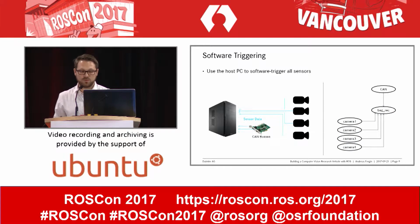The normal solution is setting up sensors at defined cycle rates and using, for example, software triggering. The image on the left of the slide shows how it could look. We have 4 cameras here that are transferring data to the PC, and the CAN bus reader, which is also transferring data. The problem is that we normally have no insight into the camera drivers, so we do not know internal latencies, and using software triggering, in the end, the images will most likely not be captured at the very same moment.